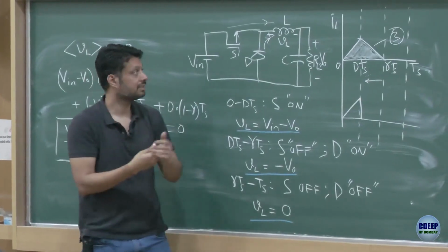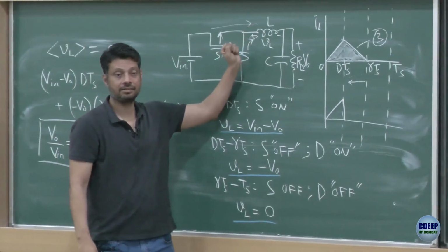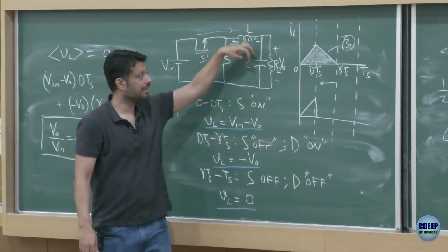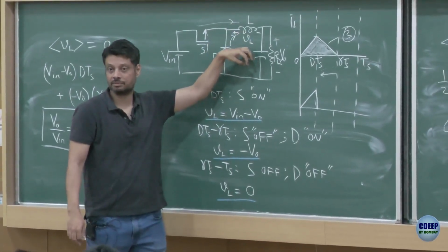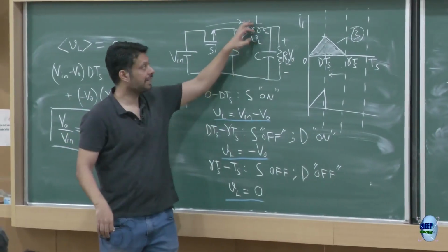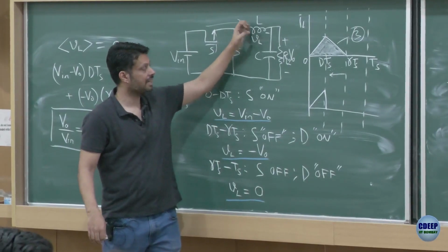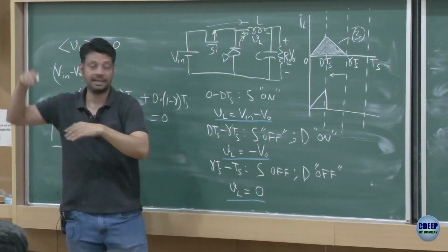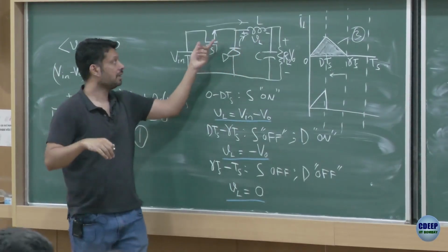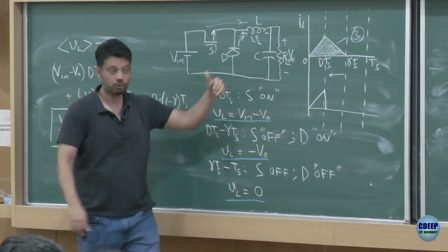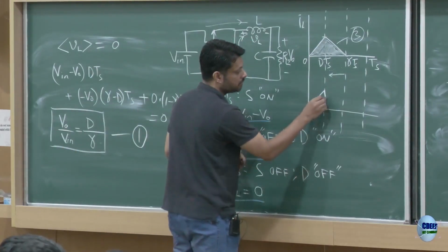So what will happen is, there is an average current here, this average suddenly you have removed. So now this average current will increase the average value of the capacitor for some time, it will be a transient phenomenon, right. So this average DC current will flow into the capacitor, and the voltage will keep on rising, right. If this voltage rises, when the switch is on, what happens to the slope? The slope will reduce. So the slope will keep reducing,